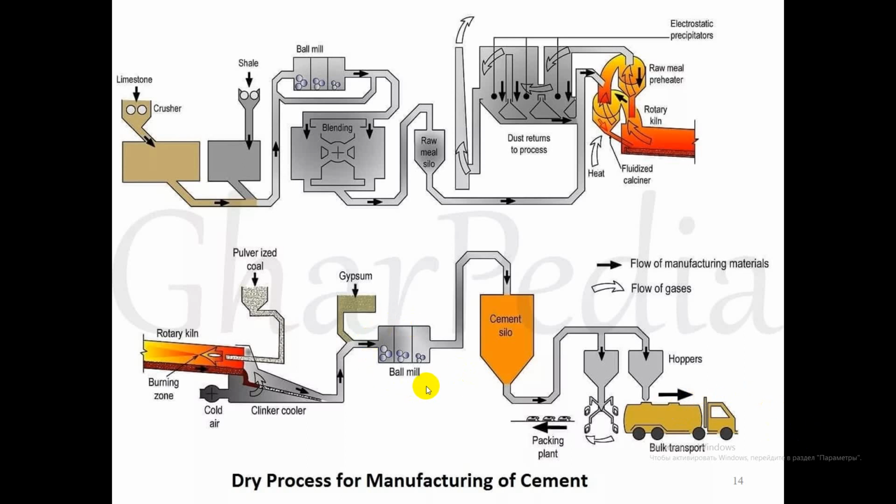During the process, we usually add some gypsum and other materials into clinker to give the final cement product different properties and usages. For example, we add gypsum to obtain the ordinary Portland cement and add gypsum and fly ash to obtain the Pozzolana Portland cement.